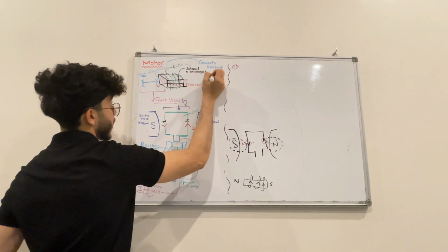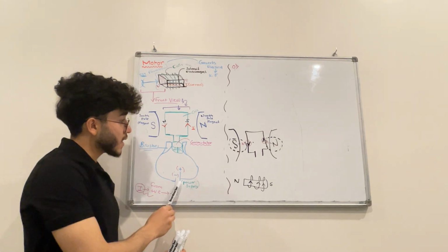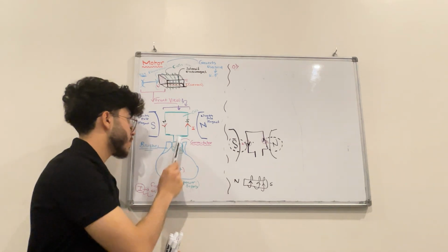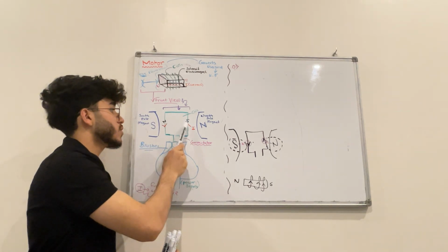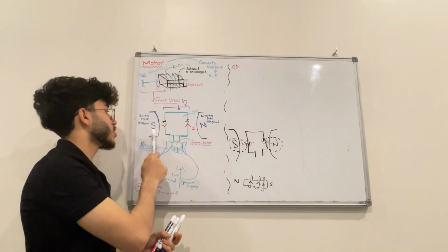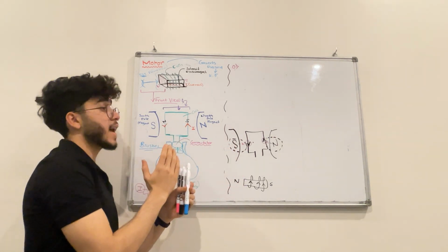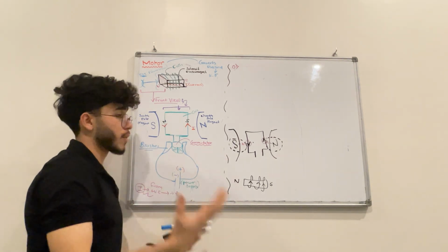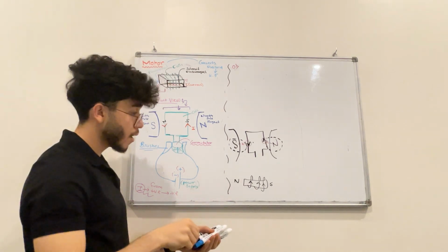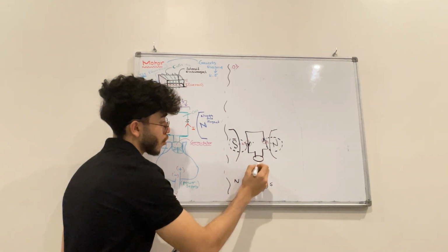to kinetic energy, okay? So when the current is passing into the coil, it makes it a half spin, induces magnetism. Current induces magnetism on the coil. The induced magnetism has north here and south here according to right-hand rule. It will make a force of attraction and repulsion with the magnetic poles I have put on both sides. It will make a half spin. And then again, it will make a half spin back to the original position. There's a problem. It's not making a full spin. To solve this problem, what will I do? I will put a commutator.